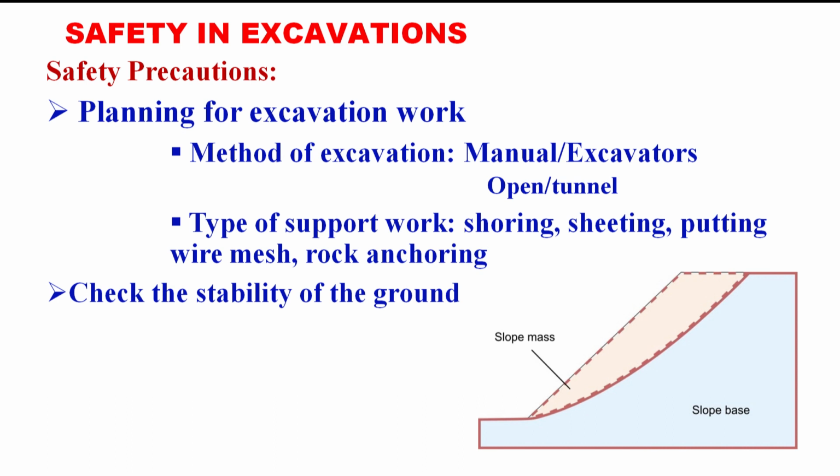Then what safety precautions can we take while doing such work? First is planning of the excavation work. As I told you, we have to think about the possibility of any groundwater source, toxic gas, or explosive gases, and plan properly.